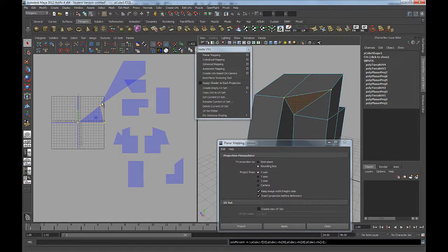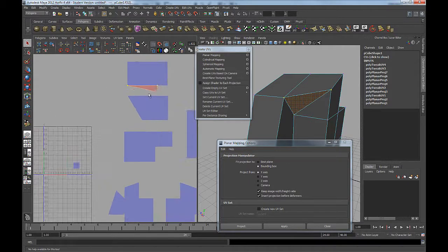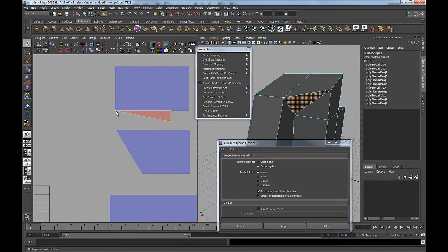Now what's occurring here shouldn't actually be occurring. This is actually an error. Basically, this should not be stretching with this object. So I'm going to undo that. The position that's causing the problem is this UV point just here.